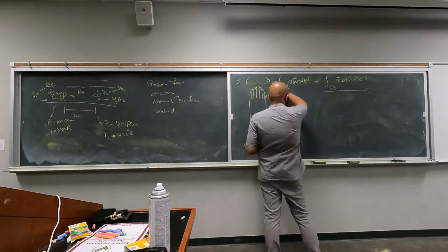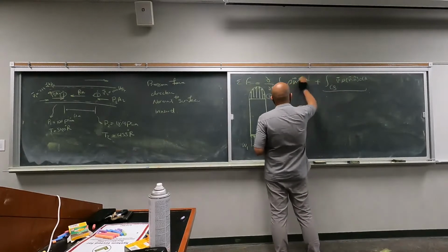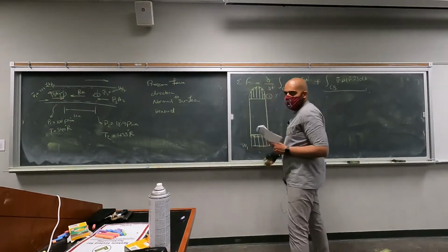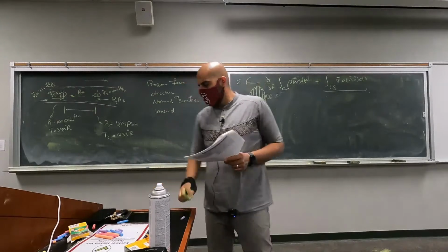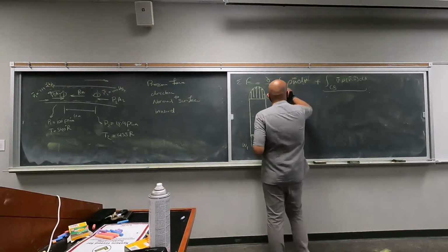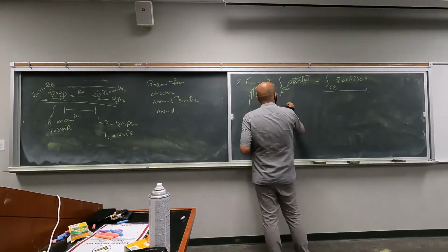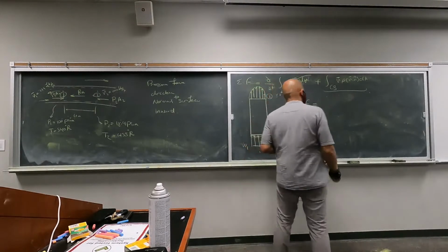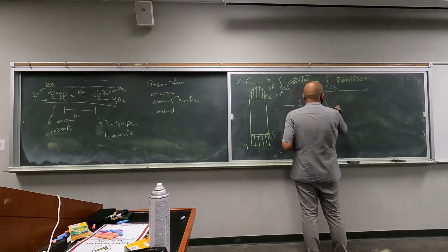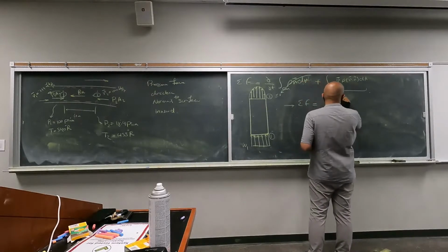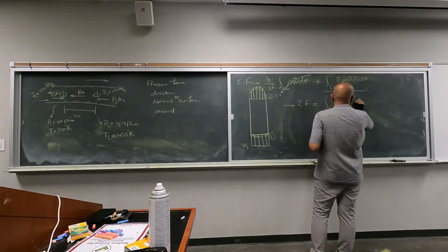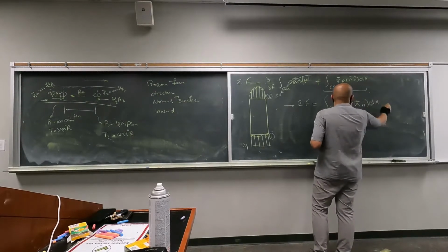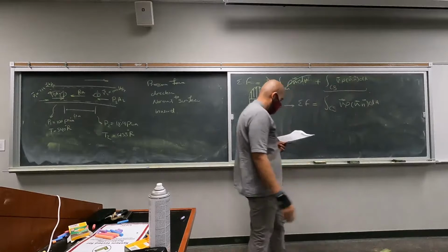So this is the momentum equation. This part goes to 0 again. Goes to 0 again. And we are going to be left with sigma F is equal to the integral over the CS of V rho Vn dA.